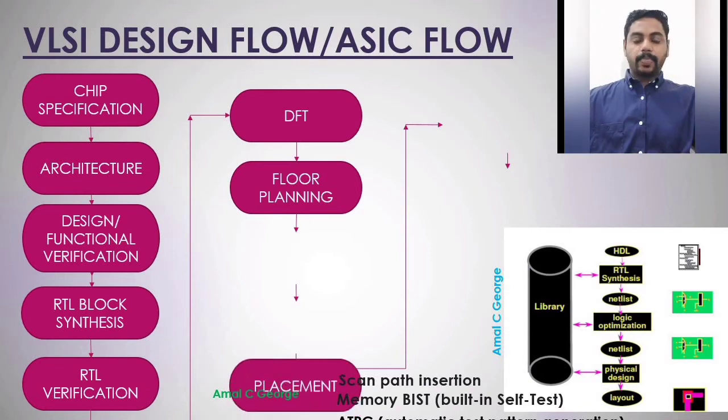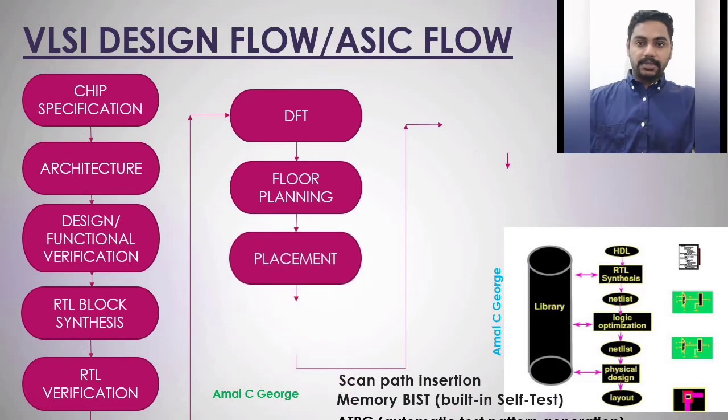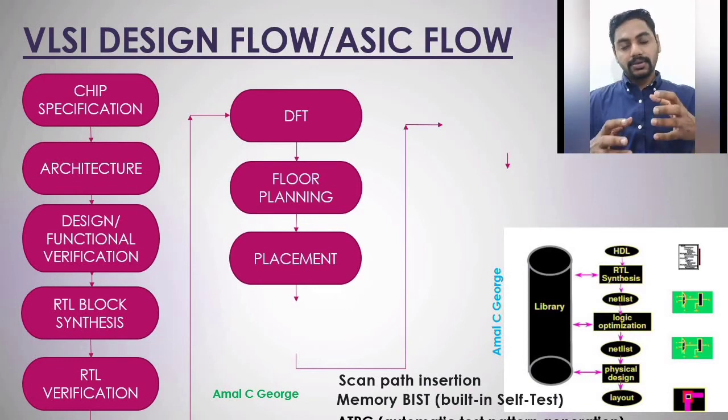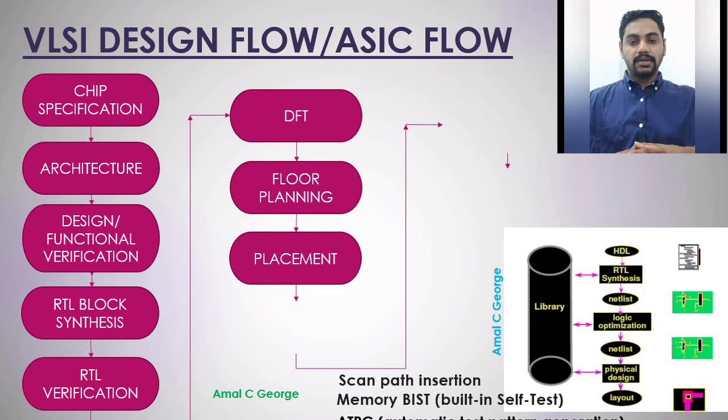The next step in the design process is placement. Placement is the process of placing standard cells in a row. A poor placement requires larger area and it also degrades the performance. So various factors should be considered during placement, like timing requirement, the net length and hence the connections of cells. Power dissipation should be taken care of. It removes the timing violations.